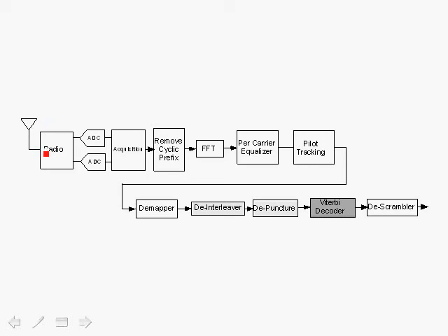We have the receive antenna and the radio and analog to digital converters. Usually there's a very tight interaction between the baseband digital signal processing over here and the RF front end. For example, automatic gain control, DC compensation, and IQ imbalance. However, in this section what we are interested in is, given the specifications and the parameters of the RF front end, what is the signal to noise ratio at the input of the ADC?